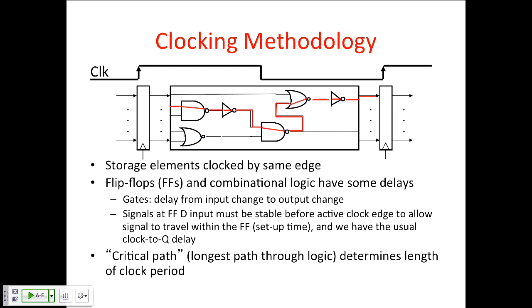So this is a good point to talk about clocking. The CPU we're going to build first is a very simple, what we call an unpipelined CPU. Every instruction takes one clock cycle. Every clock cycle, one instruction is executed completely. You do all the phases of one instruction in one clock cycle. When one clock edge arrives, you update the PC, and then all the signals propagate through the whole machine to give you the results you need to update all the state of the machine: the register file, the memory, and the program counter. If they're going to be updated, it all happens on the next clock edge.